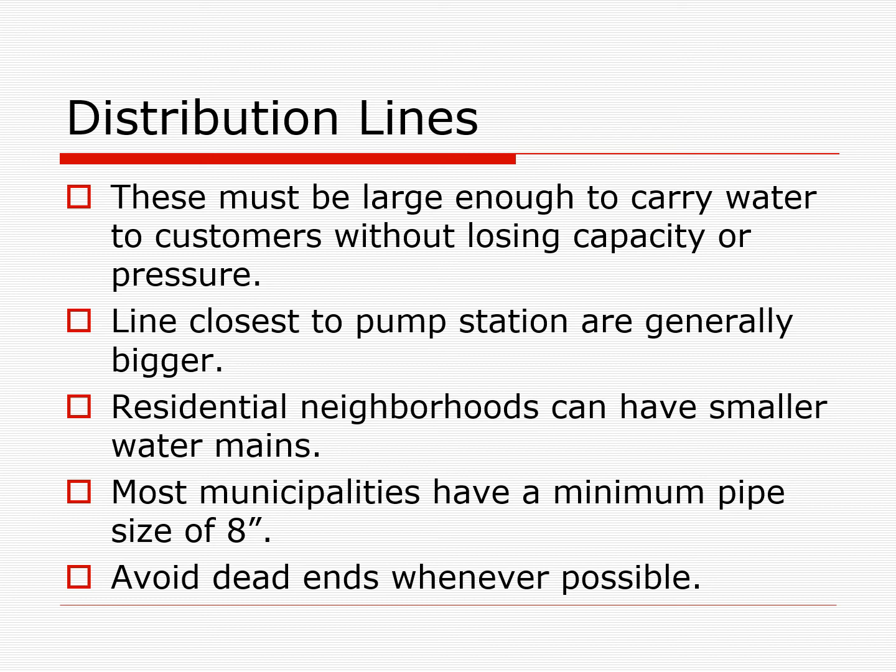Because what happens over the years, those 2-inch water lines deteriorate. They end up with deposits inside of them, so their opening is no longer 2 inches. Water pressure drops, water capacity drops, and people will have difficulty. In some of the older neighborhoods, I would get complaints that my neighbor turns on his water and my water pressure drops. And then once we would replace the 2-inch water line with a larger water main, those issues went away.